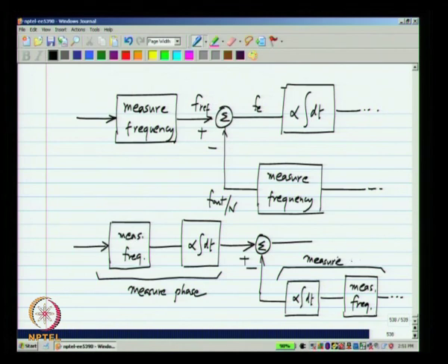This is measuring the phase of the feedback signal, the output of the counter. So, the quantity that we get here is nothing but the difference between the phase of the reference signal and the phase of the feedback signal. I will denote this signal by the subscript FB.